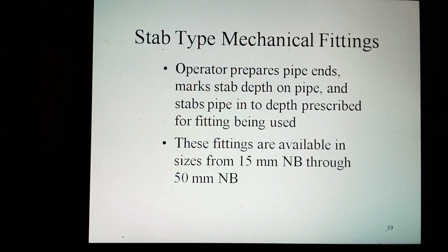With this style fitting, the operator prepares the pipe ends, marks the stab depth on the pipe, and stabs the pipe to the depth prescribed for the fitting being used. These fittings are available in sizes from 15mm NB to 50mm NB and are all to AS/NZS 2513.2.